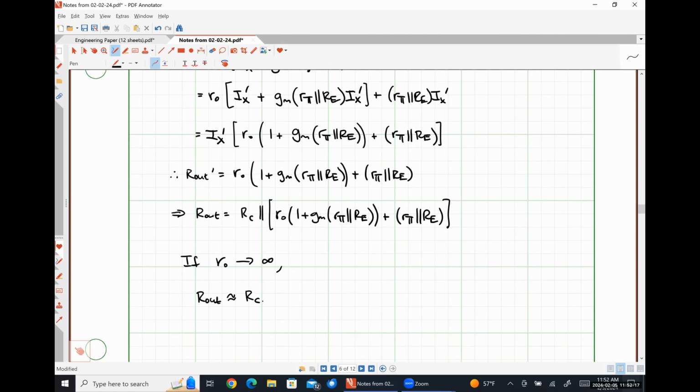So we're now at a point where we know our voltage gain, our input resistance, and our output resistance for this amplifier with emitter degeneration. So we now have a new model that we can stick in to analyze more complicated circuits.